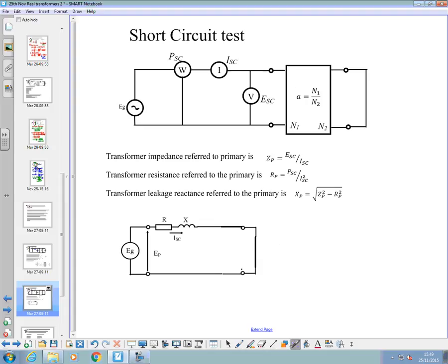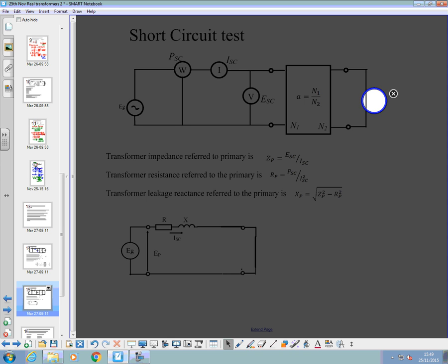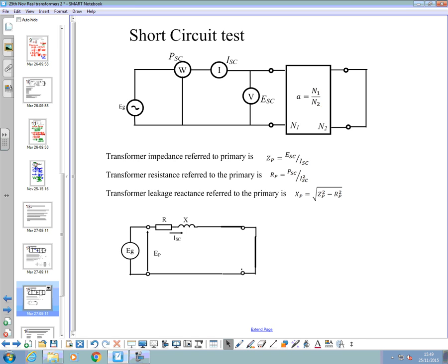So we essentially work out a voltage, or turn it up slowly, making sure we don't exceed the rated current on the primary side, secondary side as well. So it might pay just to put an ammeter in here to keep an eye on the secondary current as well. We don't want to burn that out. Okay.